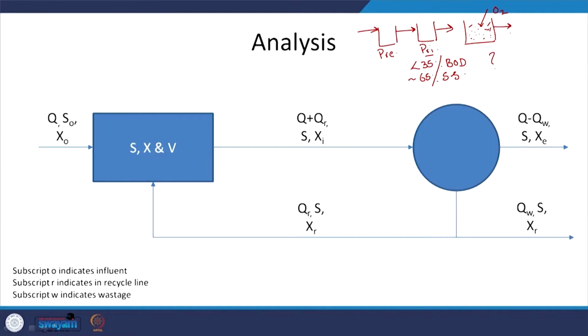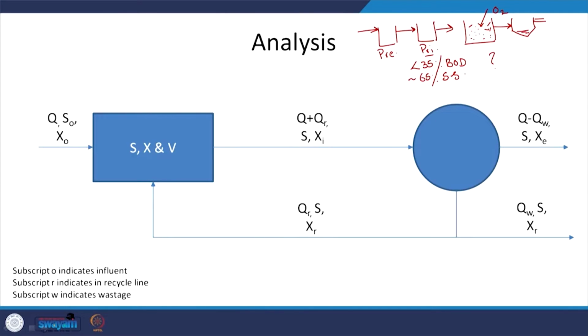And then the microbes that are formed can be settled down and removed from the system. If not, you will have issues with high microbial concentration and again organics leaving the system. So, the supernatant will be clear, and here let us say this is the water, the supernatant will be clear, while the flock forming microorganisms, which are relatively heavier, are going to settle down. So, these we will send to treatment. Again, why? Because again organic content, cells, you can't just throw it out there, it is going to lead to relevant issues, septic issues certainly.